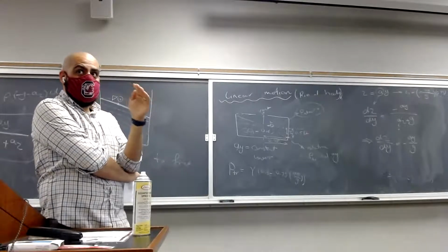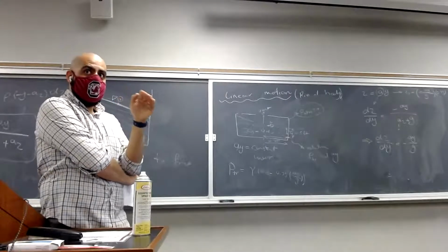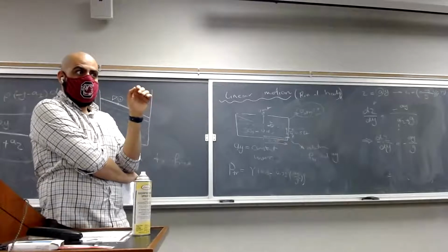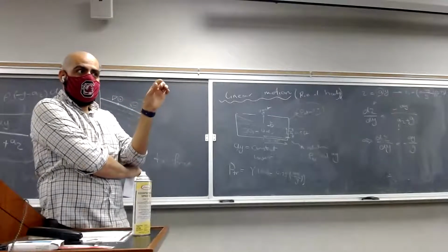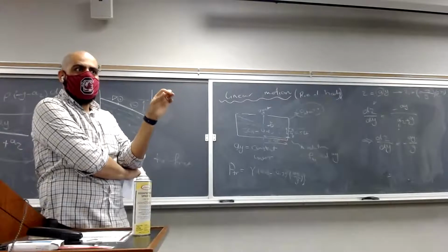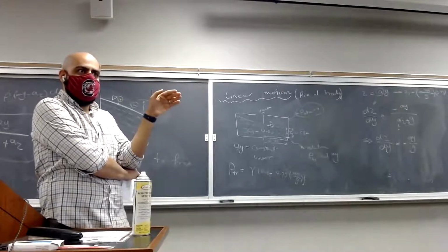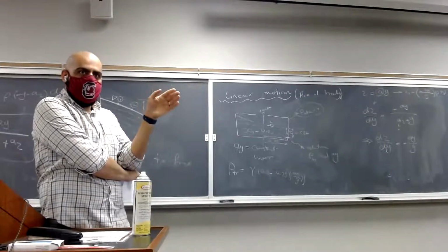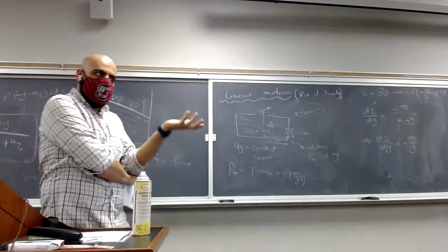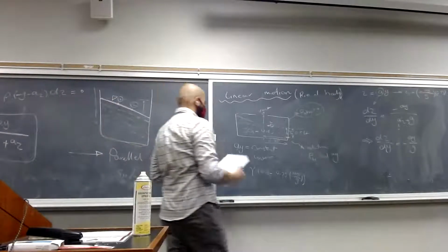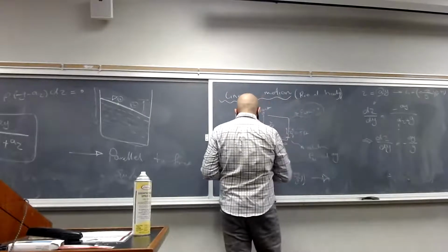Your pressure is going to increase as you increase the height, right? So free surface, what is the height at free surface? We measure the height based on the distance from the free surface. So what is the distance of free surface from free surface? 0. What does it mean for pressure? Pressure is going to be 0 as well. So atmosphere.